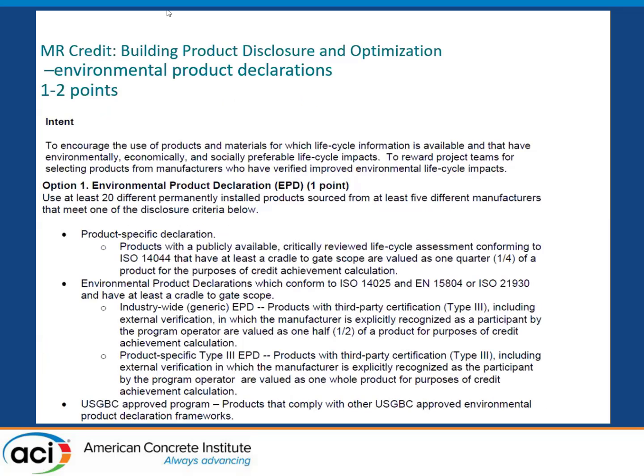So here is one of the credits that we were talking about before when we discussed EPDs and how that works into LEED. Under the materials credits, you're going to see building product disclosure and optimization. Option 1 is having an EPD declaration. What they want is at least 20 different permanently installed products sourced from at least 5 different manufacturers.